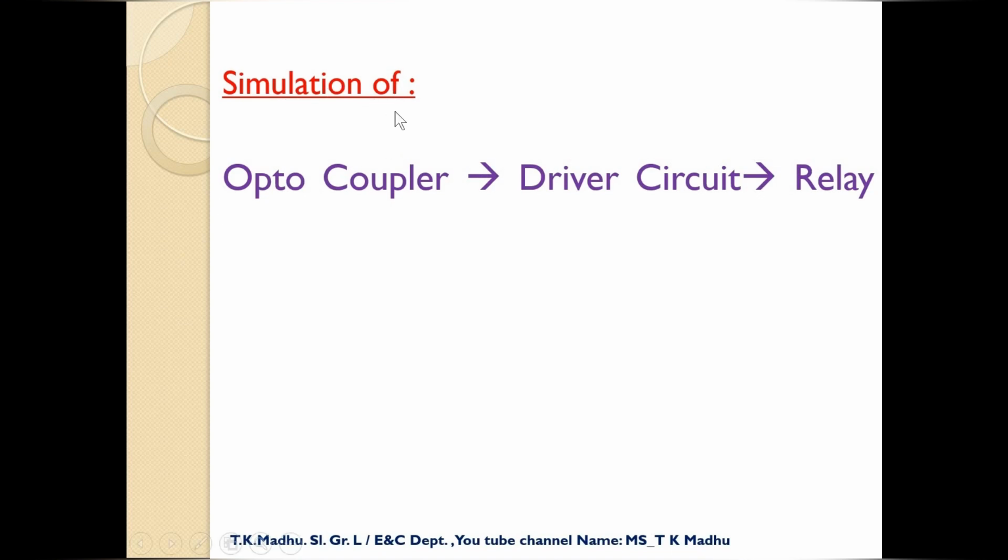So here I want to show a simulation of how optocoupler driver circuit relays are working. Now, never interface your laptop directly to the NodeMCU. Sometimes if students make any small mistake, reverse voltage can go to your laptop or desktop, and that USB section will be spoiled. So it is better to always use isolation at the output of NodeMCU, using an optocoupler, then your laptop and desktop will be safe. Make a note of this.